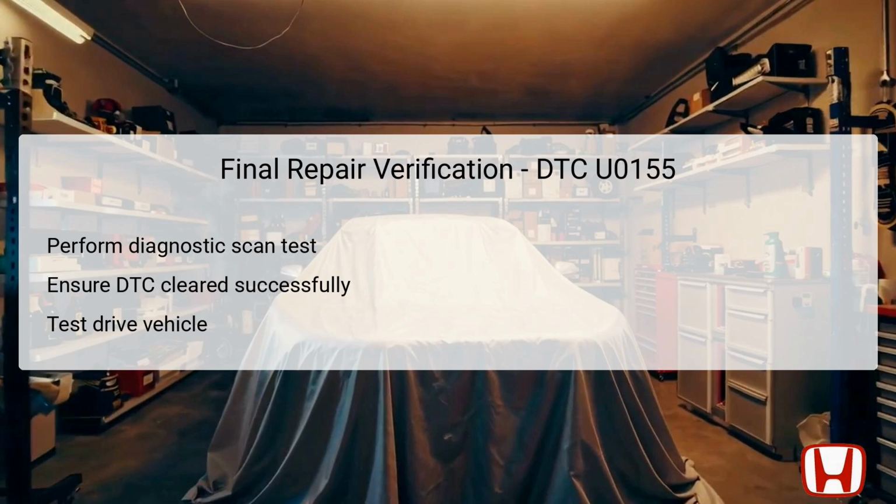After completing the troubleshooting process, it's critical to perform a final repair verification. Begin by conducting a diagnostic scan test to confirm whether the DTC U0155 is no longer present in the system. If the diagnostic tool shows that the code has cleared successfully, proceed to the next step of performing a test drive of the vehicle.